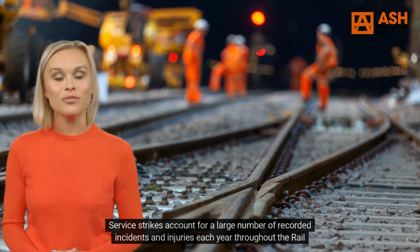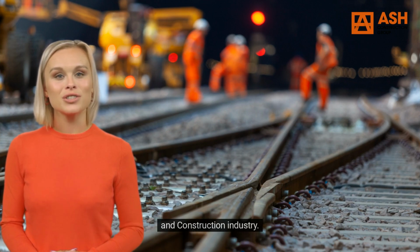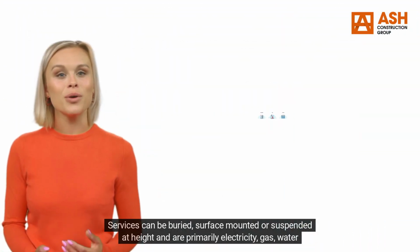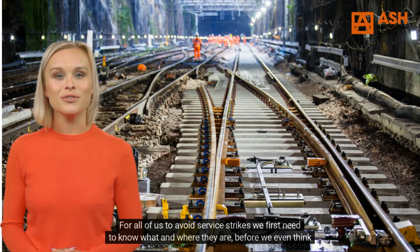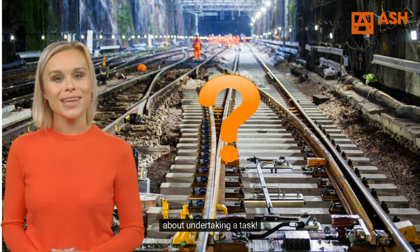Service strikes account for a large number of recorded incidents and injuries each year throughout the rail and construction industry. Services can be buried, surface-mounted, or suspended at height and are primarily electricity, gas, water or communications. For all of us to avoid service strikes, we first need to know what and where they are, before we even think about undertaking a task.